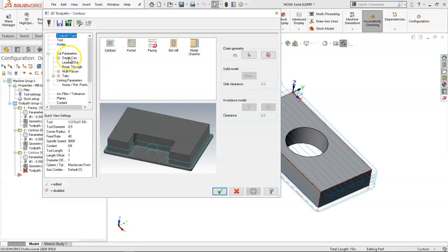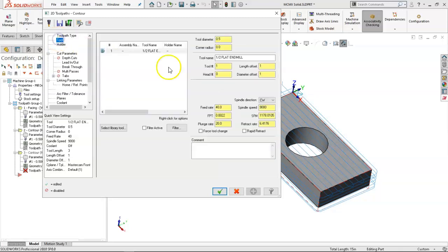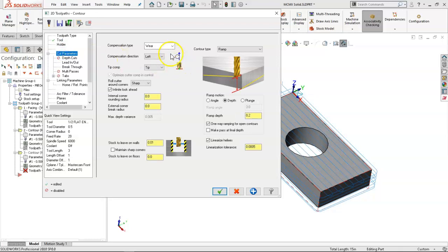and it goes to the proper side to cut. All right, so tool, retained my feeds and speeds, but for a finish pass, I'm going to slow that down, maybe 6,000, and we'll go to 20, and I'll leave it at 20, and this can be the finish. All right, not real worried about holders at this point. I've had the collisions.